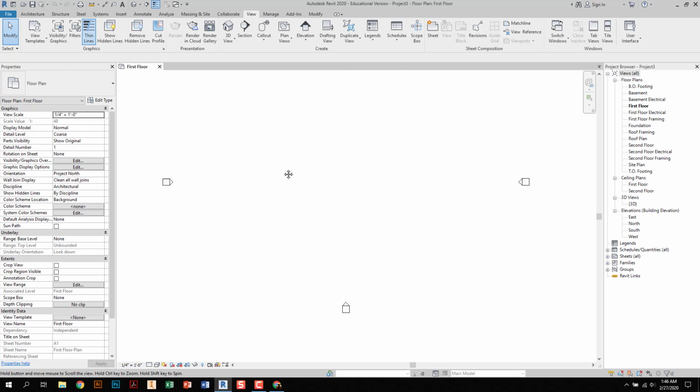If we hold the mouse button, that drags our objects around. And of course, the roller button is zoom in and out. Holding the roller button is the pan. And if you shift and roller, I guess that's zoom in this case. When you're in 3D view, shift and roller button down is our 3D rotate. Couple simple tools for you there. That's the basics of getting your Revit software set up and ready to use.